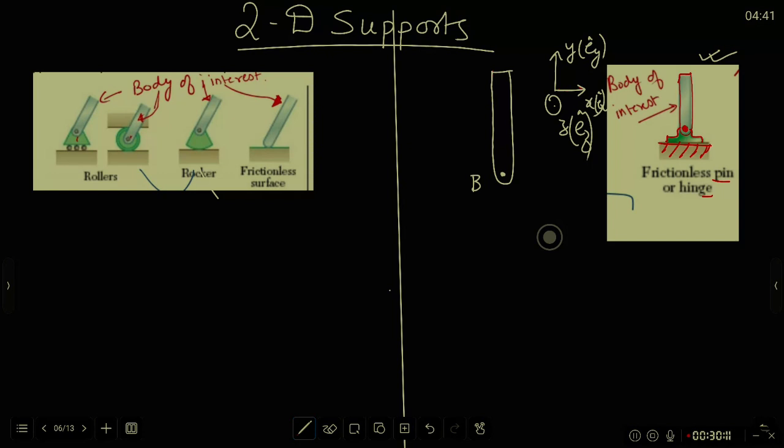The next question I ask, if I try to move the point B of the rigid body upwards or downwards, will the pin joint allow that or will it resist? It will resist, and that's why I will put Fy. So force components done. Coplanar force system, coplanar reaction force system, no need to think about Fz. Now go to the reaction torque. Cx and Cy do not matter.